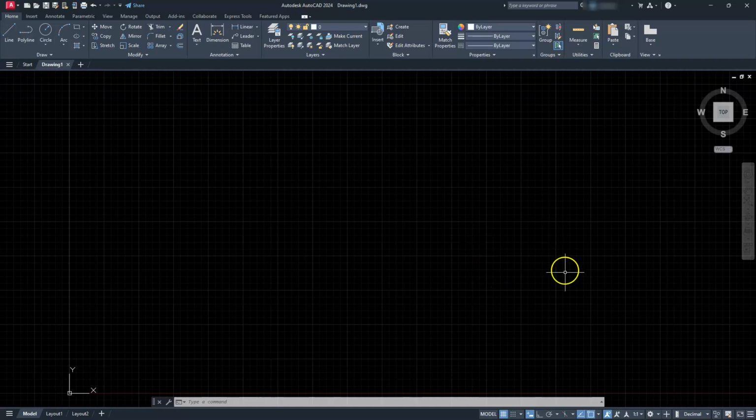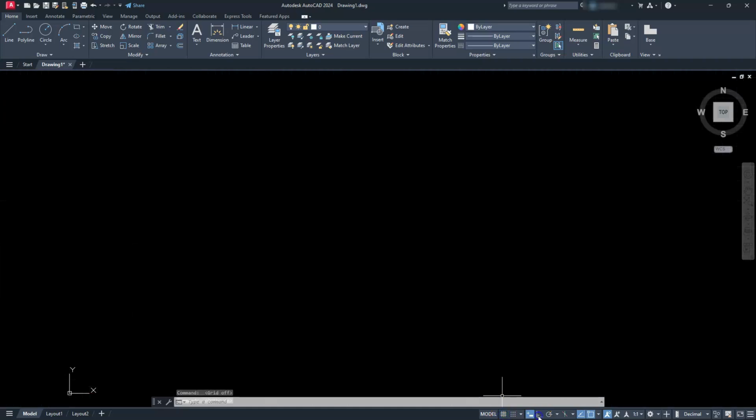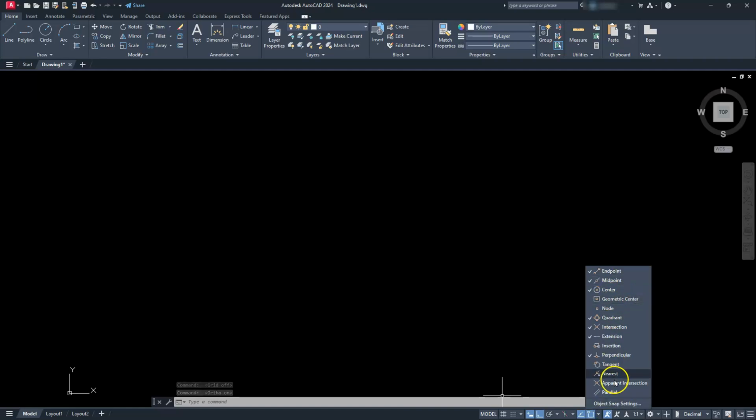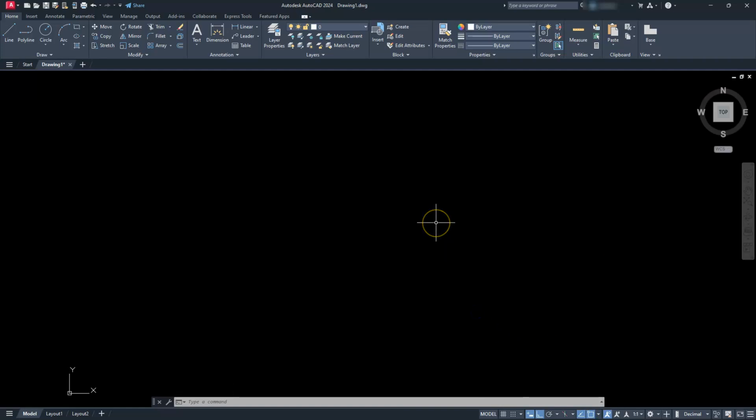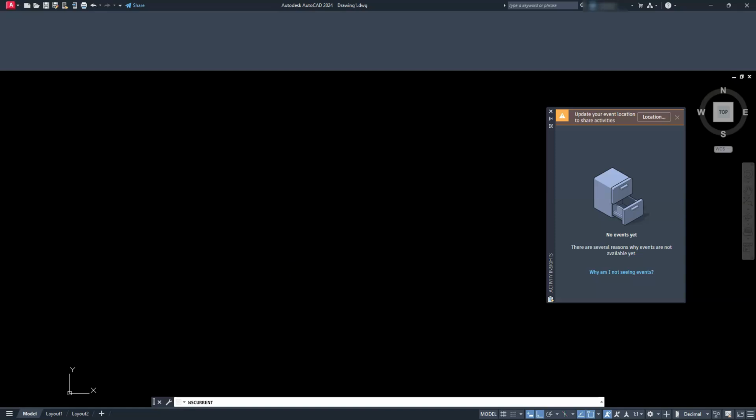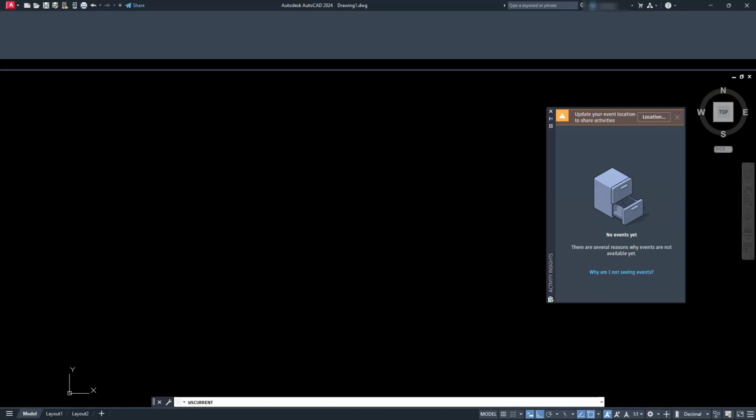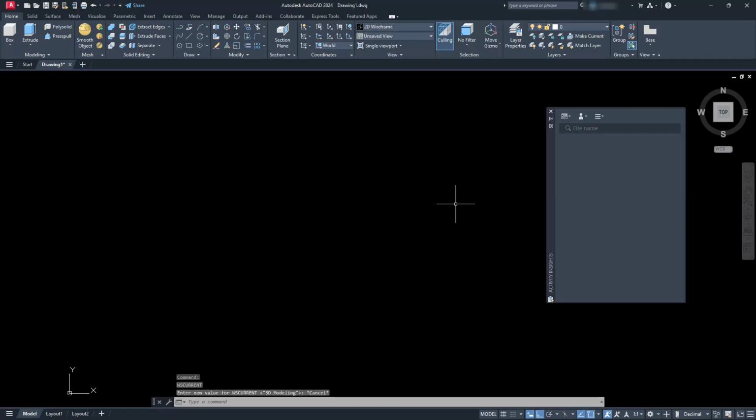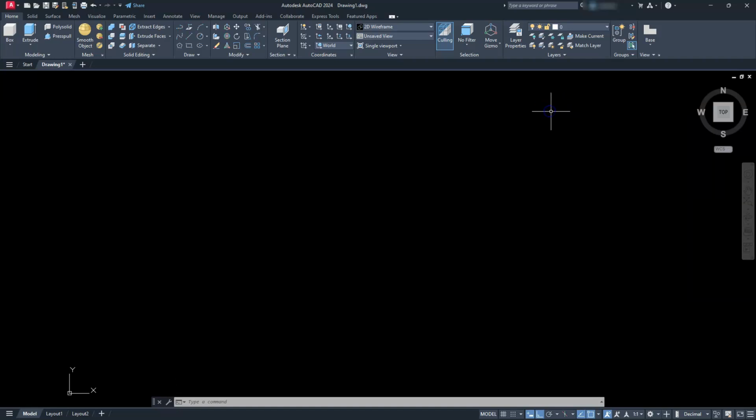Okay, so real quick, our normal stuff that we do: we turn the grid off. Let's go ahead and turn our ortho on, and then we'll take a look at the running O snaps that I have set up. All right, and I'm going to automatically jump to doing AutoCAD 3D. So I'll hit the little sprocket here, click the flyout next to it, and go to 3D modeling. All right, you're going to give AutoCAD a little bit of a moment. It's going to change your ribbon and start setting up your settings for 3D AutoCAD. I'm giving it one more second here. Then let's go ahead and hit close on that.